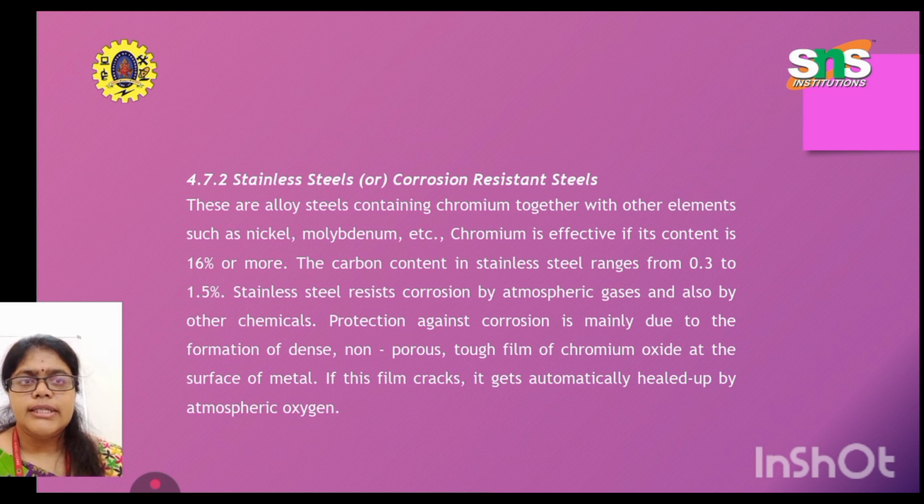Next is the stainless steels or corrosion resistant steels. Steel itself is a corrosion resistant material, as we all know. These are alloy steels containing chromium together with other elements such as nickel, molybdenum, etc. Chromium is effective if its content is 16 percent or more. The carbon content in stainless steel ranges from 0.03 to 1.5 percent.